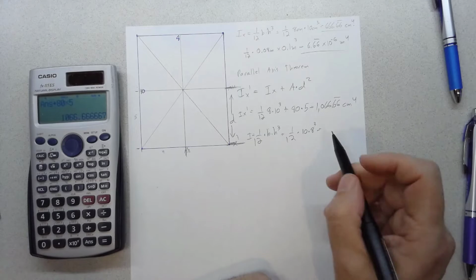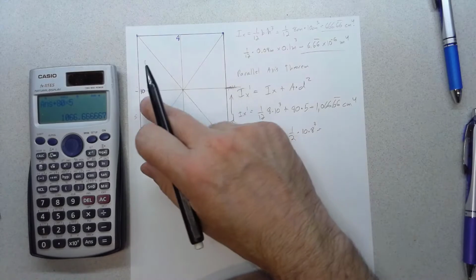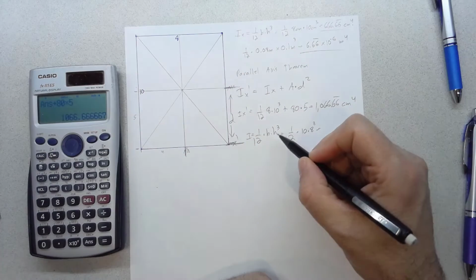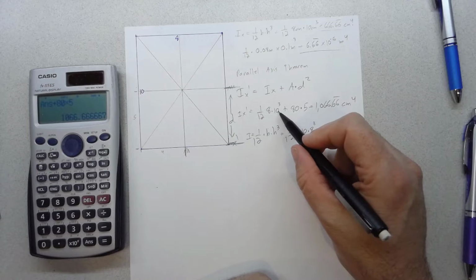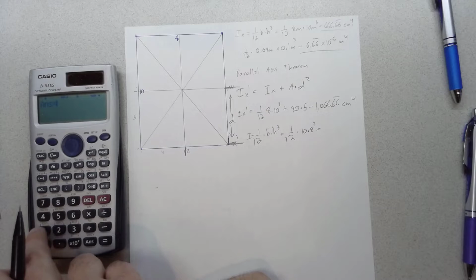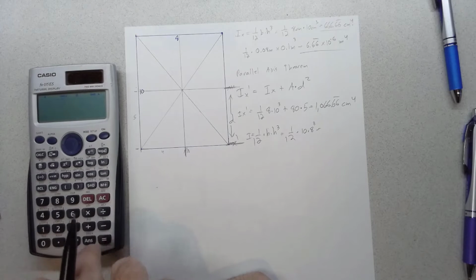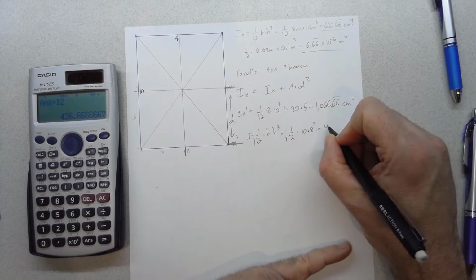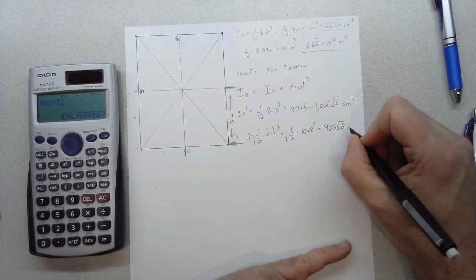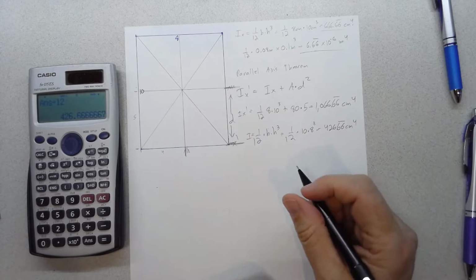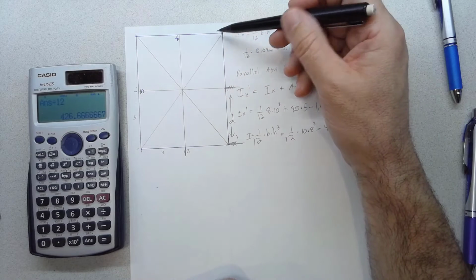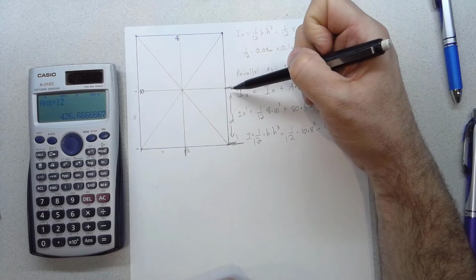And so you can already see that it's going to be less stiff in bending about this axis than it was about this axis, right? Because we're using the same two numbers, 8 and 10. Just before we were cubing 10, and now we're cubing 8. So 8 cubed times 10 divided by 12. And the answer is 426.66 repeating centimeters to the fourth. So just pointing out again that a beam is always stiffer the more of its material is located further away from the axis you're bending about.